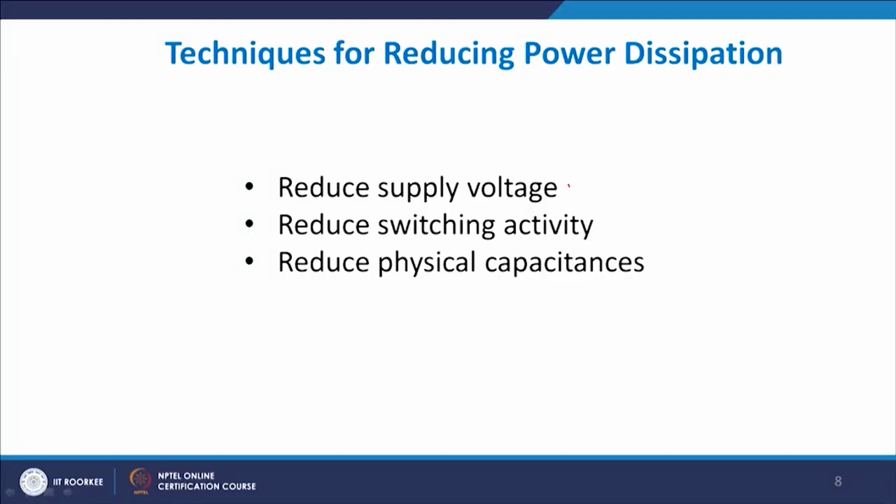Generally, PDP is a constant for any system. PDP and EDP are constant. So, energy delay product and power delay product are constant, which means that if the power dissipation becomes high, then that can be only accommodated provided your system becomes slow. So, TP has to go down. TP going down basically means that your system is getting faster in this case. Now, this is what you get from the power delay product, energy delay product concept.